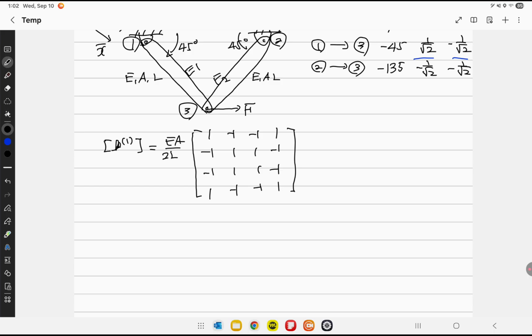And to help you understand the location where that element stiffness goes, I often write it as U1 degree of freedom, V1, U3, V3. So this stiffness matrix connects U1, V1, U3, V3. This is new information, so take a big breath, take a moment, and try to understand. Any question?